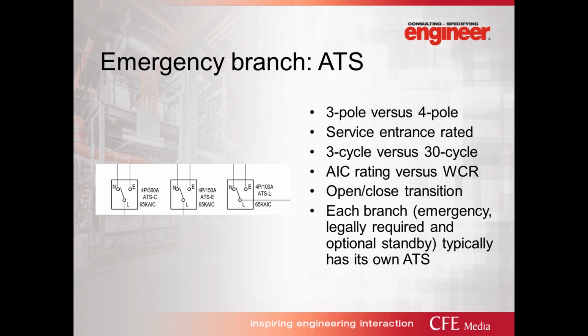The open transition transfer switches are more cost effective. The closed transition might be required in healthcare facilities and data centers where the customer would prefer to avoid that split of a second changeover in power.